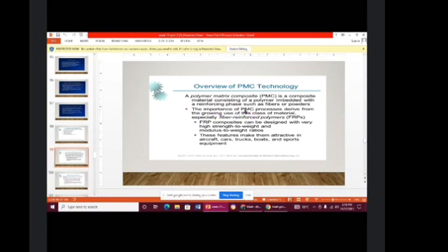The importance of polymer matrix composites derives from the growing use of this class of materials, especially the fiber reinforced polymers, or FRP. FRP composites can be designed with very high strength-to-weight and modulus-to-weight ratios. This feature makes them attractive in aircraft, cars, trucks, boats, and sports equipment.